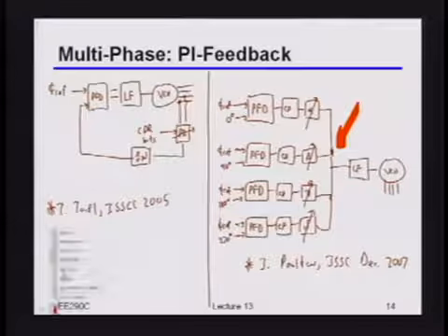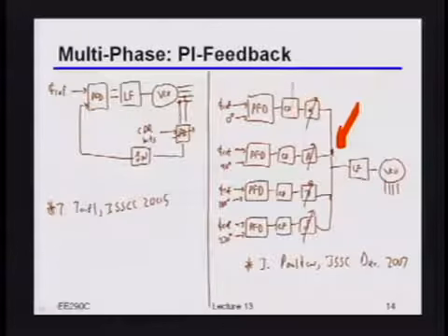Oh, yeah, absolutely. In practice, what you really do is adjust the currents in the charge pump. Or you may even have some switches and then just have two charge pumps with adjustable currents. There are lots of ways you can build this.